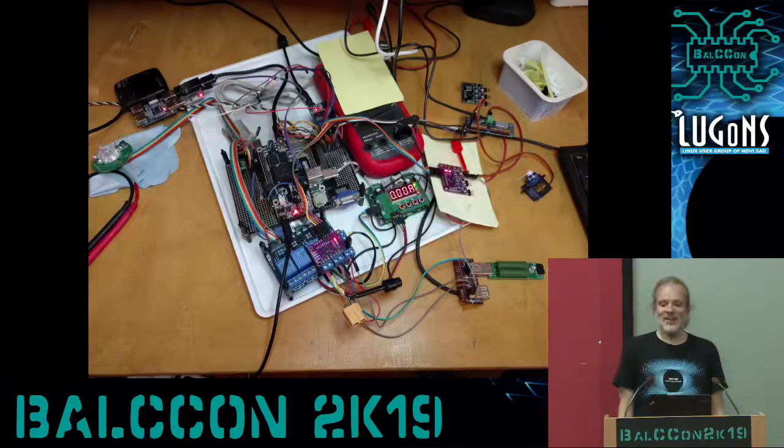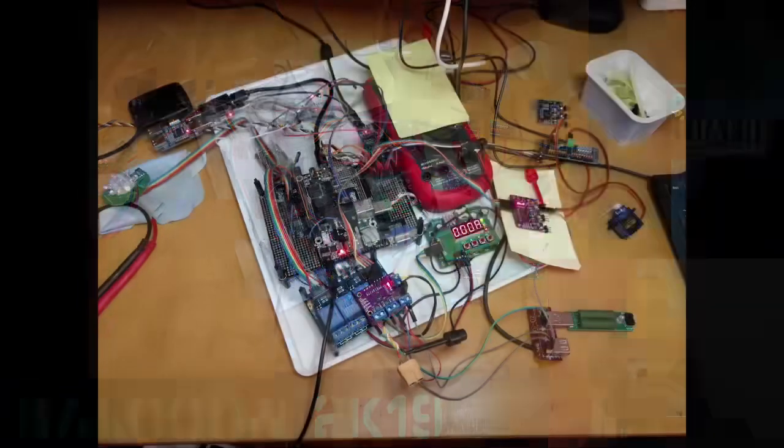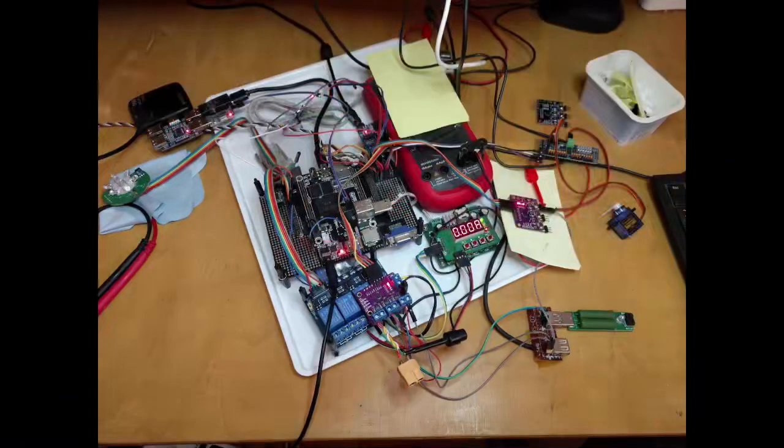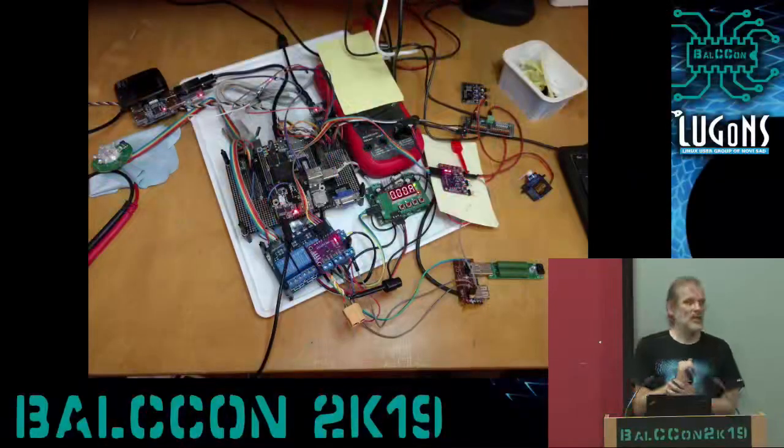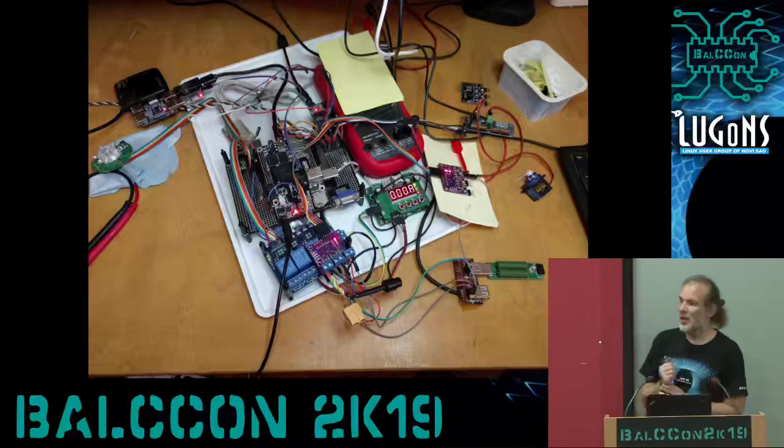And this is the current state of that QB board you saw before. This is basically my bench power supply, which has 4 relay-controlled outputs and open source firmware on the step-down converter on the right below the multimeter. The multimeter is connected through serial to this box, which enables me to control and measure the voltage and current I am feeding to my devices, which was very, very useful.